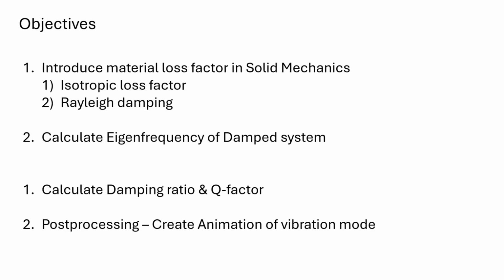Next, we will define the material loss and perform an eigenfrequency simulation to obtain complex-valued eigenfrequencies. Using these results, we will calculate the damping ratio and the Q factor of the system. Finally, we'll show how to create animations for each of the resonant modes to visualize the dynamic behavior of the structure.